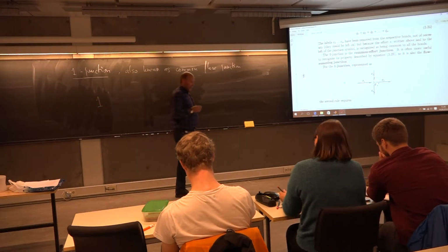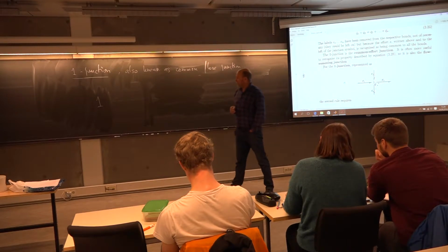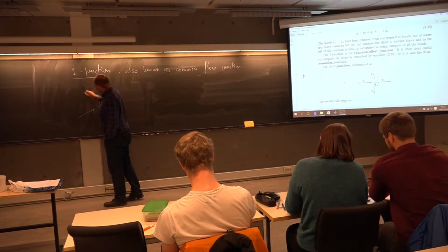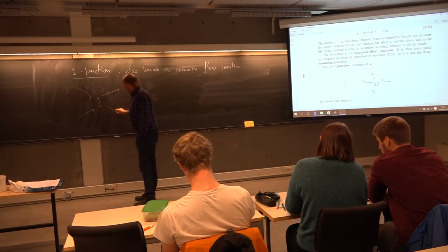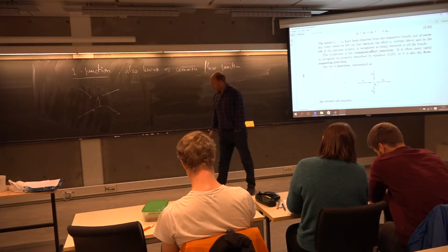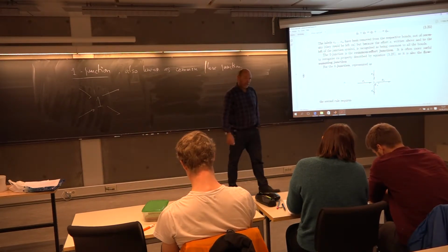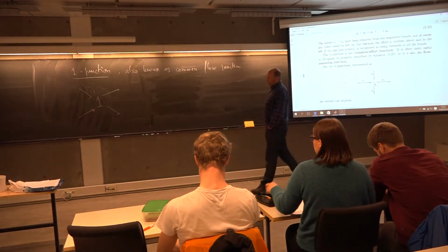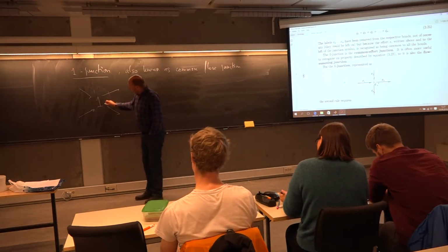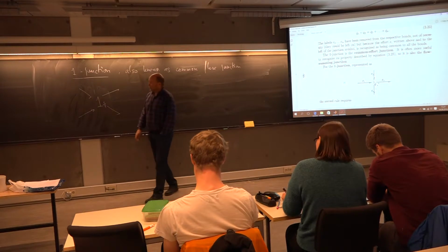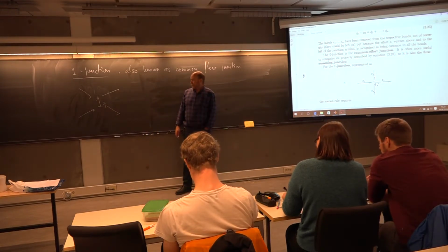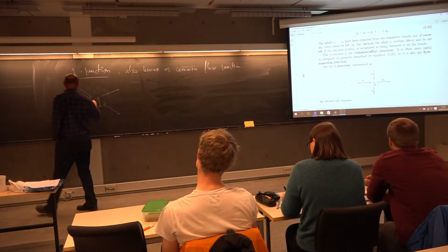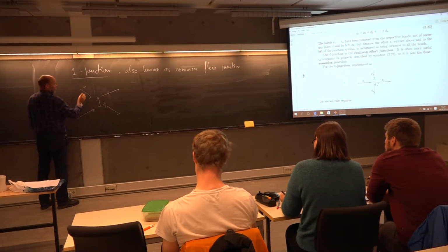And again, you will draw some bonds that enter the 1 junction, and some bonds that exit it, like this. And now the flow will be the same on all these bonds. So instead of writing the Q dots on every bond, you can write one single Q dot here and say, this is the flow that is the same on all bonds around this 1 junction. But the efforts can be whatever.